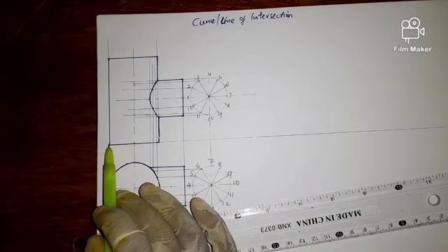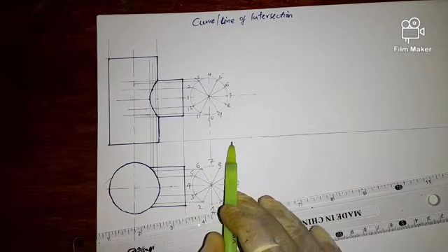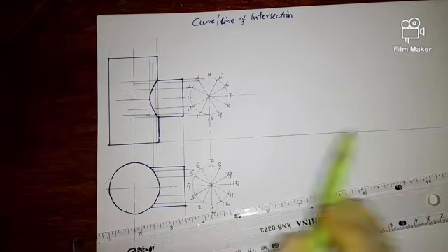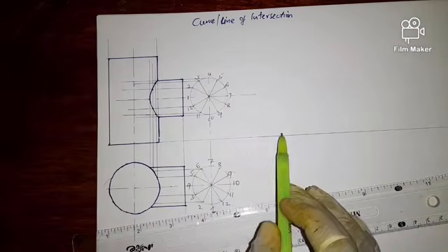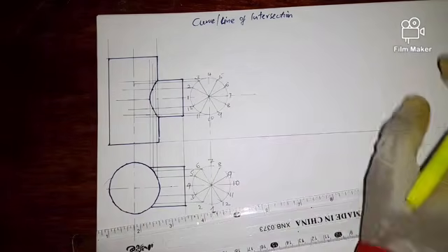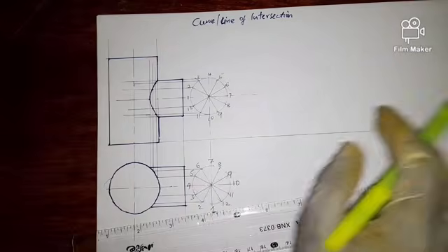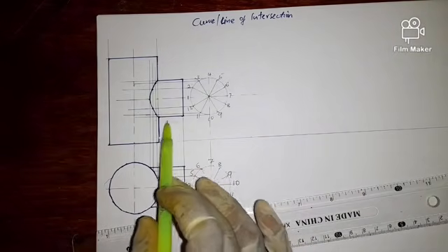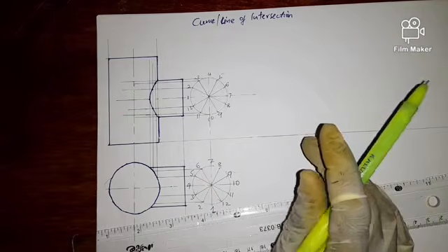It means the circumference assumes the base or the length. Then the height assumes the width. So we are going to have a rectangular shaped development here. Then we'll be able to transfer these points on our rectangle.